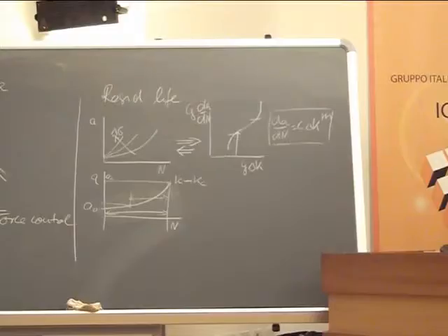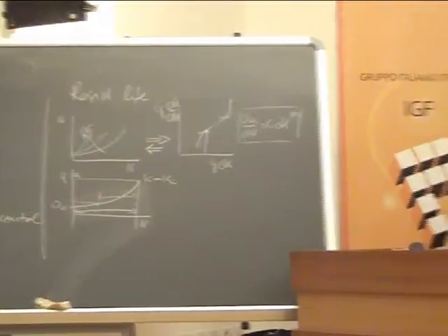And then, for given crack sizes, you can determine the life of a material or a component, and you can construct S-N curves, including endurance limit.